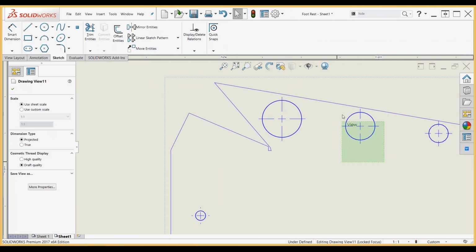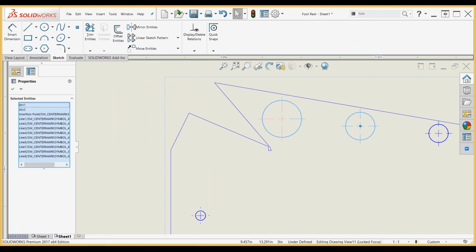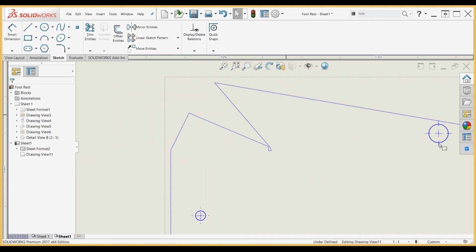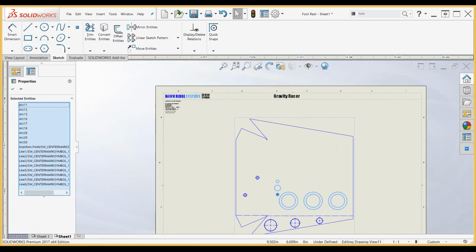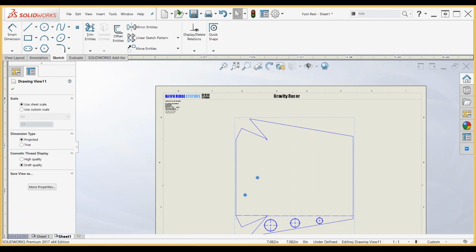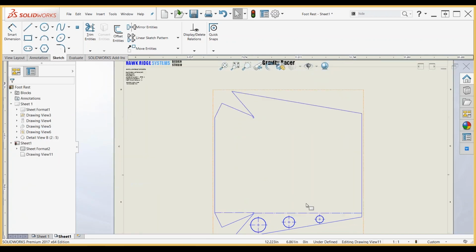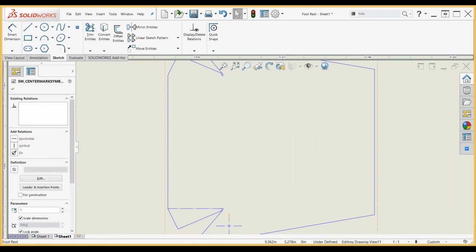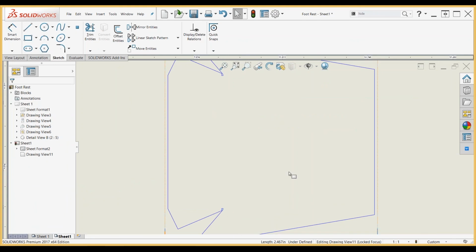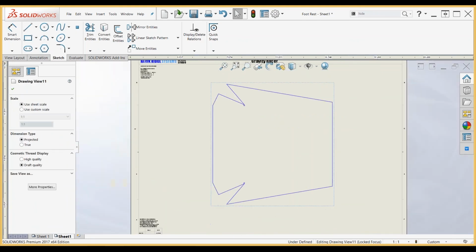So stage one here is assembling the brake disc, but if you look at our model, we have the axle in there, the caliper, and a whole bunch of pieces that don't actually exist when you're putting that hub down. So I'm going to leverage a display state where all of those components are hidden. So using a combination of configurations and display states, I can show the different stages of my assembly process.